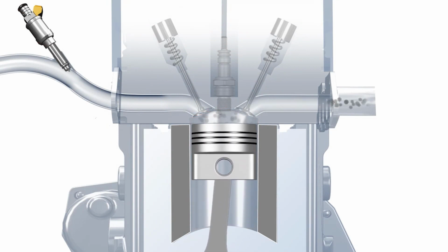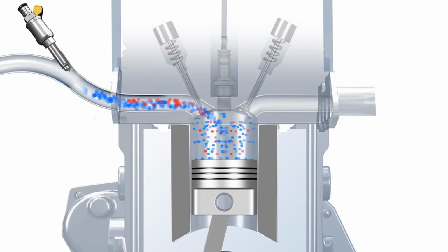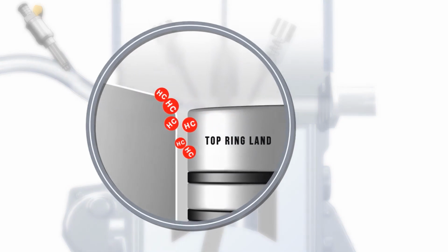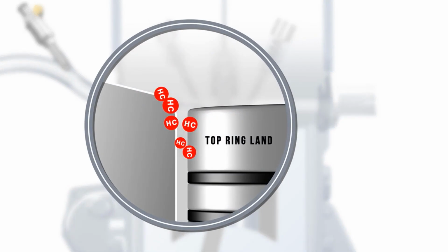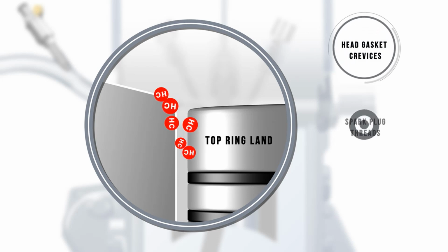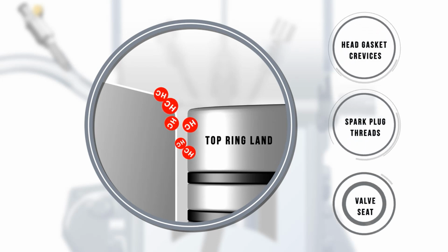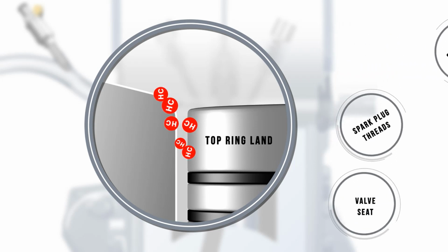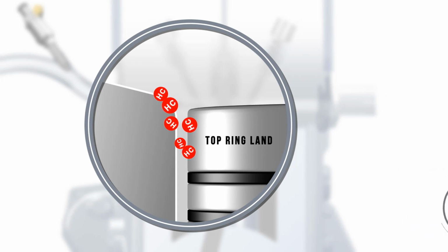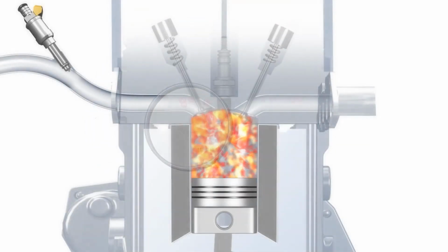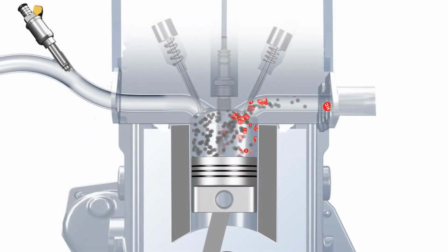Even in a normally operating engine, when the intake charge is compressed into the combustion chamber, portions of the mixture are forced into areas around the top ring land and cylinder wall, any crevices formed by the head gasket, spark plug threads and the valve seat. These areas are somewhat sheltered from the flame front and do not ignite during the combustion process. On the following exhaust stroke, the unburnt fuel mixture exits the combustion chamber via the exhaust valve as hydrocarbon emissions.